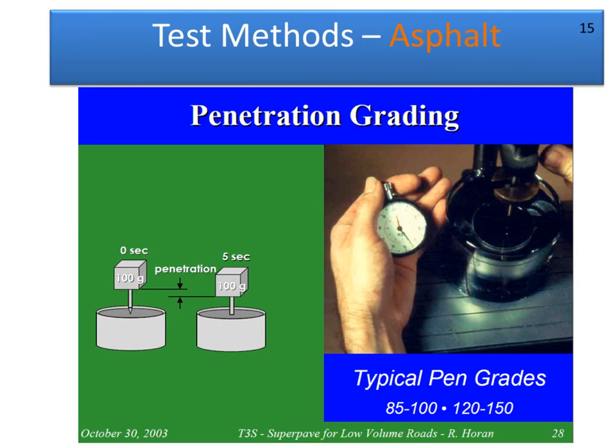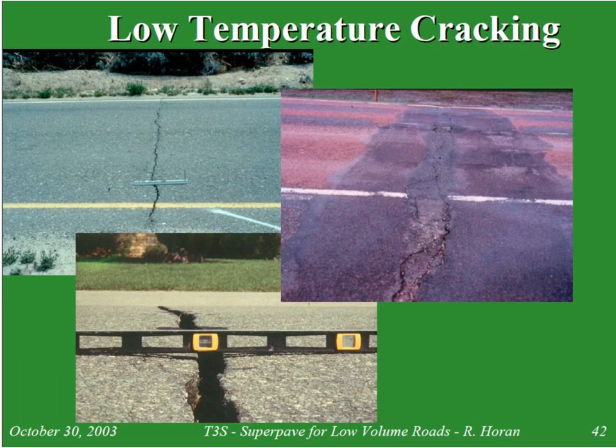The higher the penetration number, the weaker the asphalt is, so to say. The less stiff it is, the less hardness it has. So it's much softer, I should say, maybe that's a better word to use. The higher the penetration number is, the softer the asphalt is, so the more the plunger is able to go into the asphalt. The lower the penetration number, obviously, the harder the asphalt is. It also gives us an indication of the viscosity: if it's more viscous, it's typically harder and has a smaller penetration number, whereas something with a larger penetration number is more liquid and therefore less viscous.